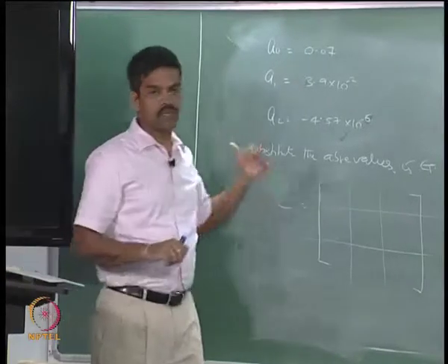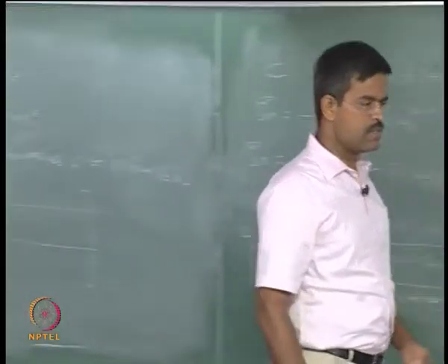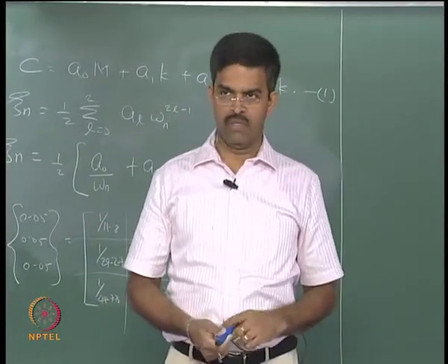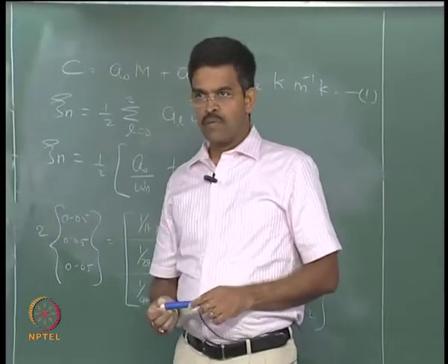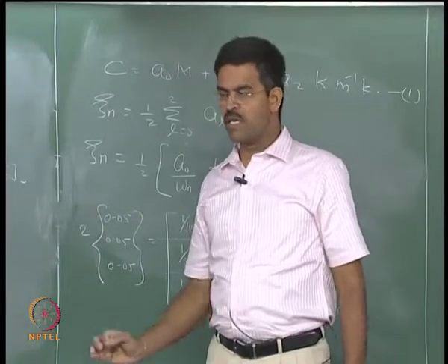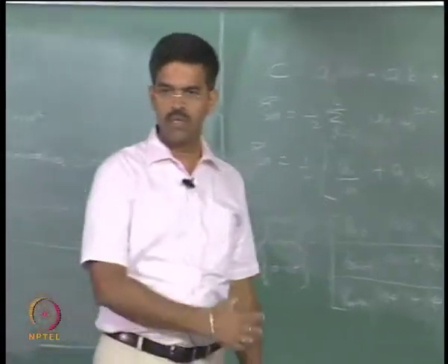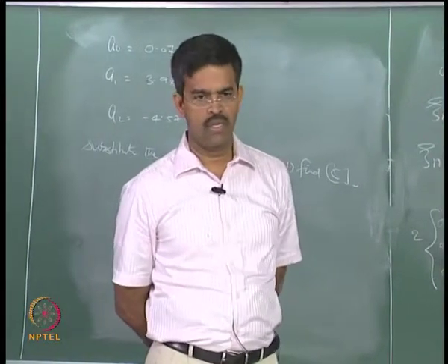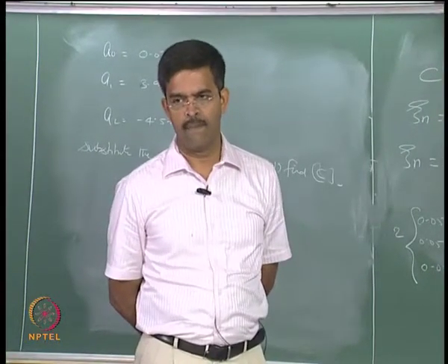That is how I estimate the damping matrix using the Caughey series, which includes the contributions from all frequencies omega 1, omega 2 and omega 3, keeping the condition that zeta, the damping ratio, is the same or uniform in all the modes of vibration. Damping ratio, not the frequency, is assumed to be the same in all modes of vibration.